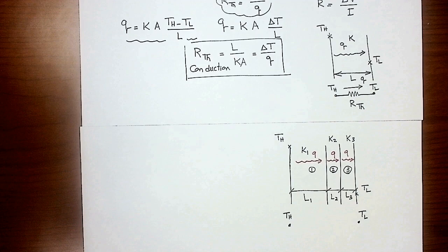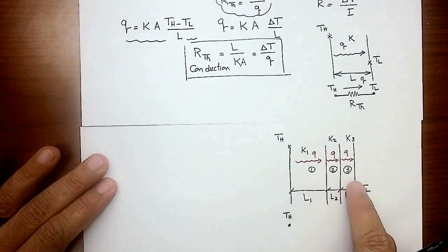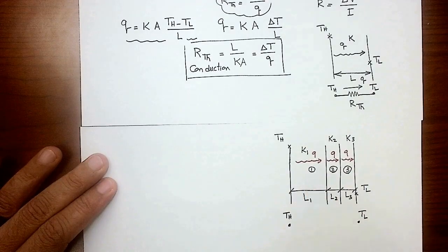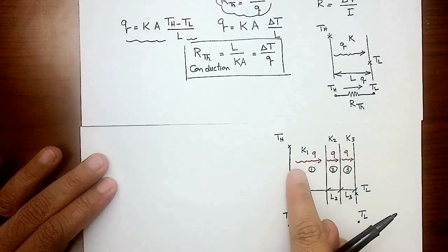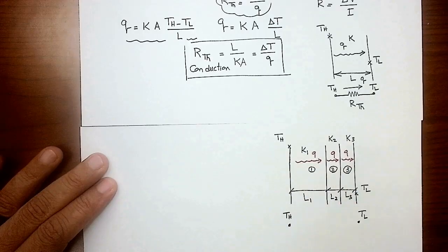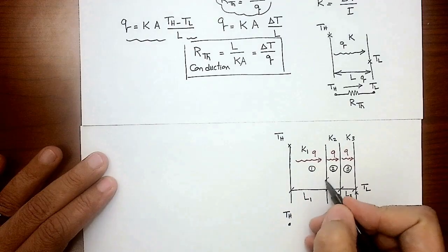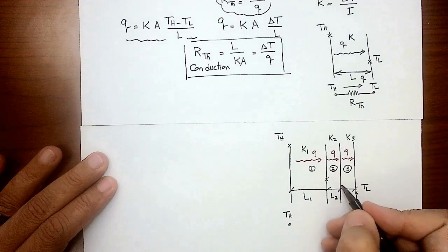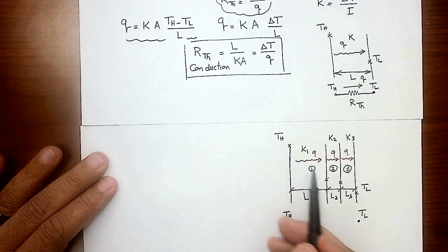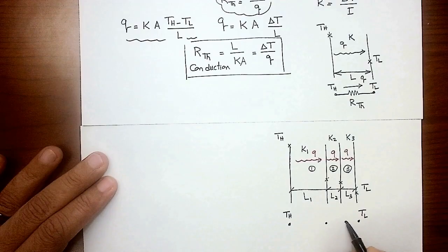When the resistances are connected in series, which is telling me that I can represent each one of these walls by a resistance, but keep these resistances connected in series to guarantee that the current going through all of them is the same. So I know that face will be at a given temperature. That face will be at a given temperature, and temperature is going down from here to here. So I'm going to present a node and a node here.